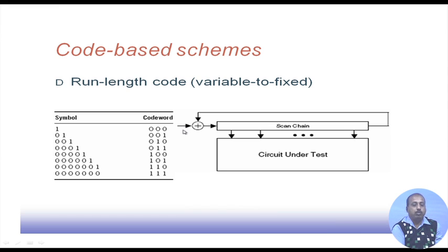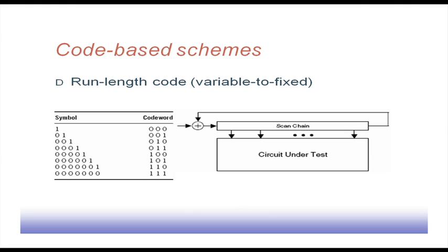That happens due to the correlation between the test patterns, and there are don't cares in the test pattern. So, don't cares can be filled so that we get more similar test patterns, so that these zeros will occur more frequently. So, the bits will be the same, as a result I can feed a 0 here.